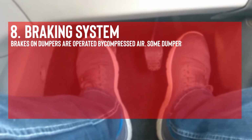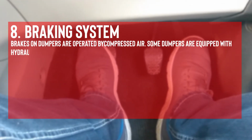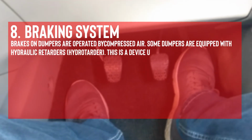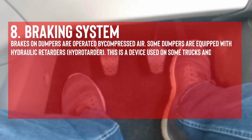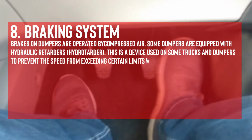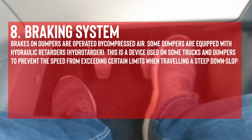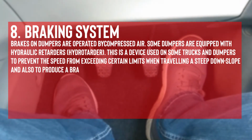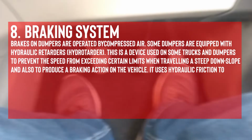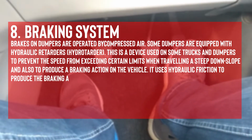Number 8. Braking system. Brakes on dumpers are operated by compressed air. Some dumpers are equipped with hydraulic retarders. This is a device used on some trucks and dumpers to prevent the speed from exceeding certain limits when traveling a steep down slope, and also to produce a braking action on the vehicle. It uses hydraulic friction to produce the braking action.